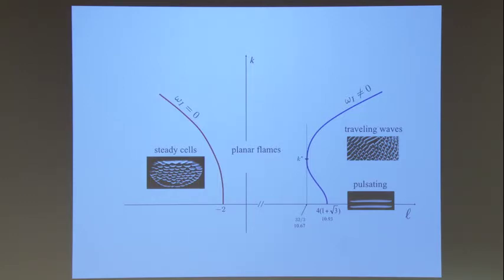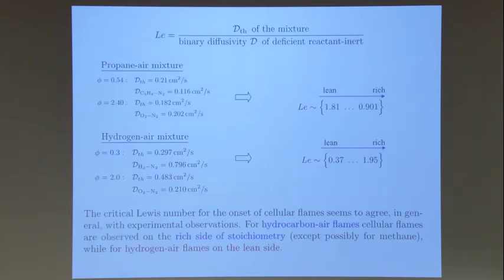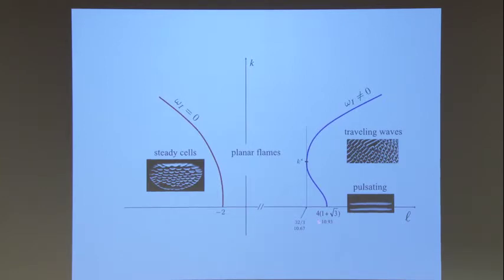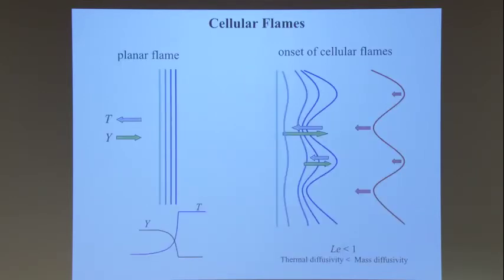They have been observed in the lab when the flame is near a burner, like a flat burner, due to the heat loss. Because what happens is that heat loss just brings down the critical value. I think it's mentioned in one of my other slides. You're going to see it in a minute. I'm almost done here. So this number goes down when there is heat loss, and so you can observe that instability. So anyway, this was just to explain the nature of the cellular flame.